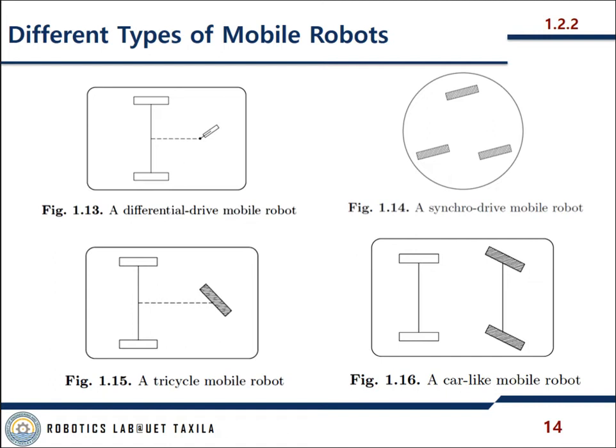As I said, the first motor controls the rotation of the wheels around the horizontal axis, thus providing the driving force through traction. The second motor controls the rotation of the wheels around the vertical axis, hence affecting their orientation. Note that the heading of the chassis does not change during the motion. If you want to change the direction, first the vehicle is stopped, and then its direction is changed.